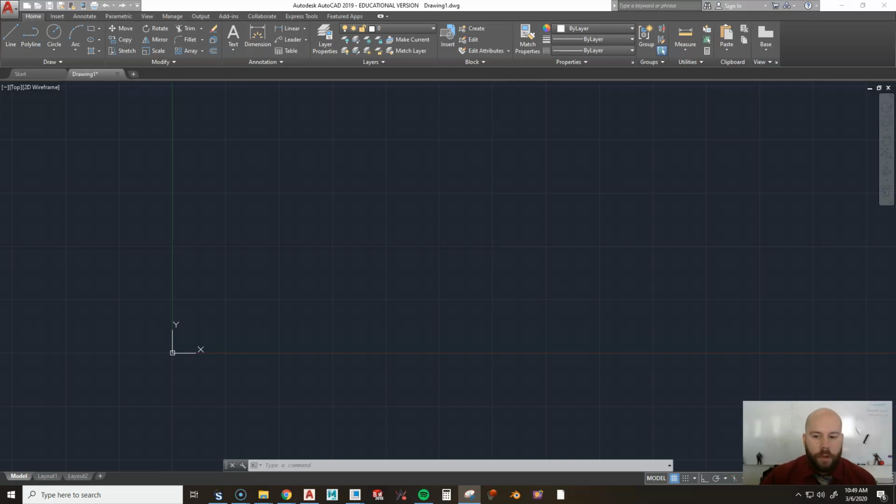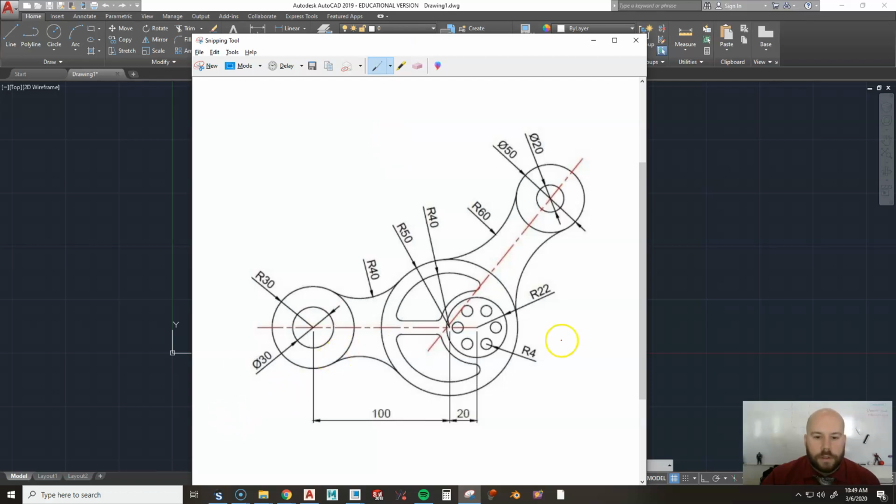Okay, so I'm going to move this to the side. I can look at it the whole time. Actually, I'll bring it back for a second. So to me, if I'm looking at this piece on a design and drawing side of it, the thing that jumps out to me is this is kind of like a linkage system. It might just be a piece that someone made some crazy shapes to give an exercise to. But what I usually try and do is find the origin, or where we're going to start from. We could start from a couple different spots. We could start from here, or we could start from the center of this larger circle. This is probably what the whole thing's based on for the pivot. So I guess we'll start from the end over here, but just understand you can start from really anywhere. It's just going to be easier to follow dimensions this way.